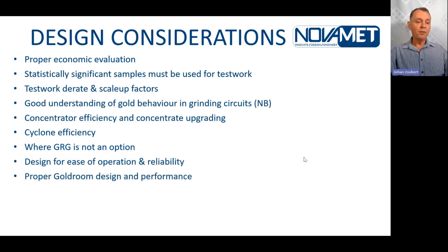We then also now have a beautiful concentrate that we've spent so much money and time to get, so we need a proper downstream recovery system. A lot of people skimp a little bit on this because it is quite high in capital and also not the easiest of circuits to install, but spend the time and effort and money to design a proper downstream. Personally, I still believe that leach reactors and electrowinning is the better suited option with gravity concentrators.